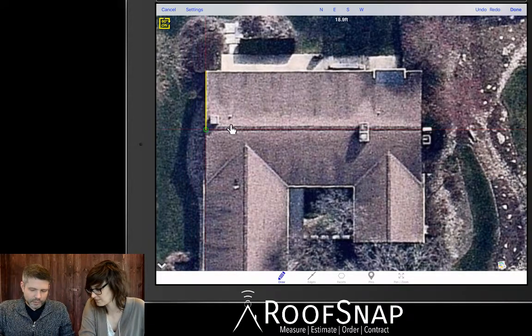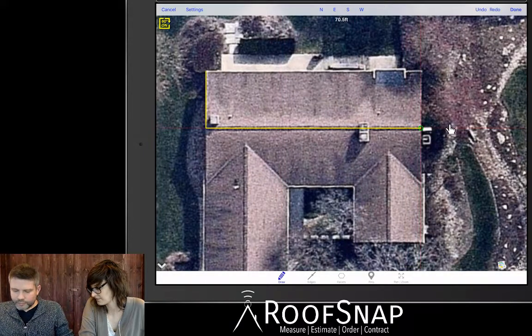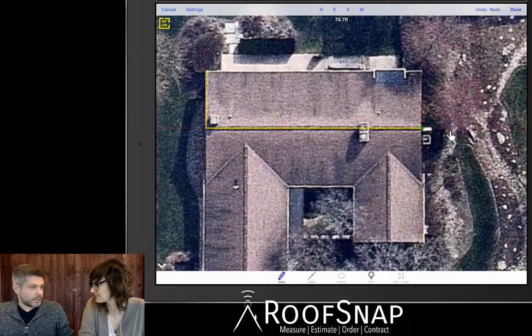All right, so let's draw that line, and then let's turn and draw all the way across the ridge. Now we've come to the end here, and same thing. It wants to be horizontal now. So this is the 90-degree function coming into play. We are at 90 degrees from the last line. It's nice and straight. Now we snapped this image as straight as we possibly could as well, because if this image were crooked, then 90 mode and its functionality breaks down. So you want to get this image perfectly level before you snap it.